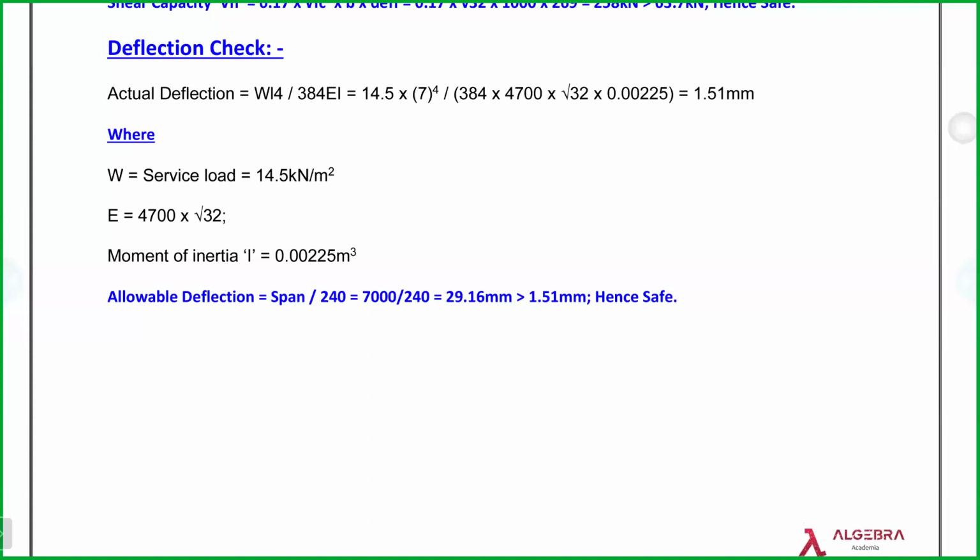The people are making a lack of understanding in all those checks; they will carry out by using the shorter span. When it comes to deflection check, what they used to do, I think, sir, both spans would be deflecting, right? Then I'll take, for a bit of cushion, the longer span. Understand what I'm trying to say? Actually, longer span is completely wrong. You get my point.